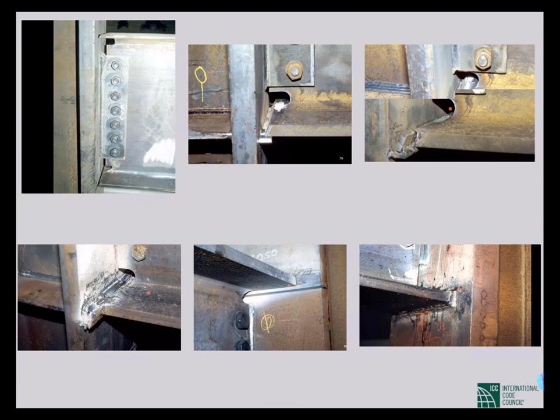Now, after doing that, the backing material is removed, and all the weld tabs and backing materials are removed. You remember it was mentioned that in this protected zone, no extra attachment can be there. All the attachments that are used during construction should be removed. In the middle bottom picture, you can see the top flange. Here again, you have the backing material, and this is being prepared for the welding.